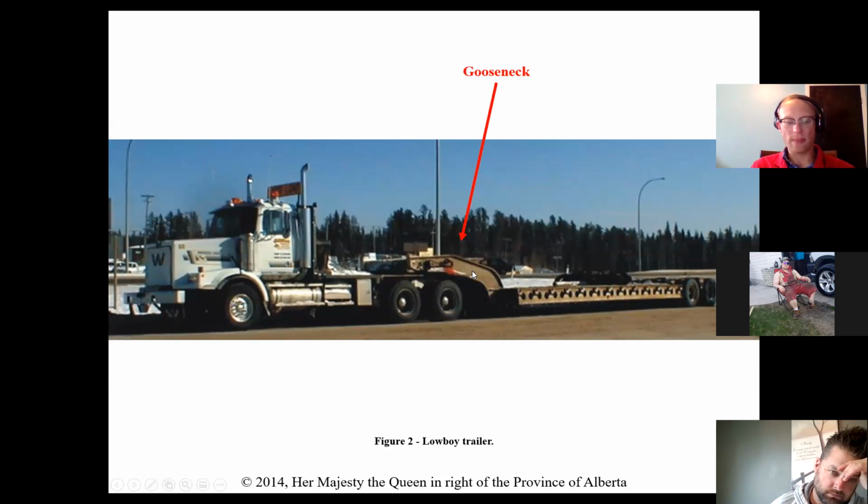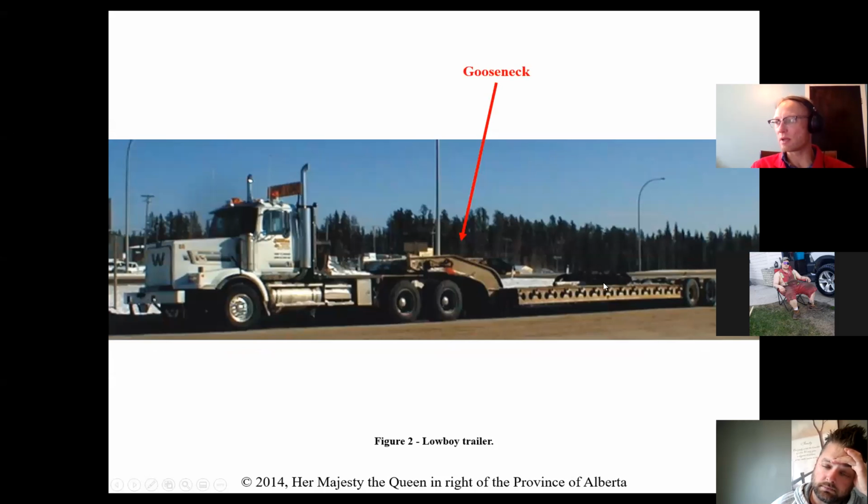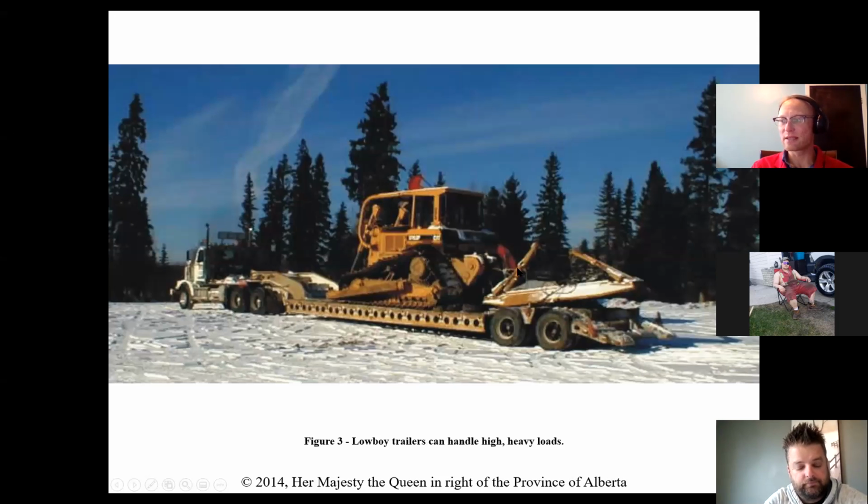This can haul like wood, something that isn't too heavy. If it gets a really high load up here, not a big deal. Whereas something that's really heavy, with a high center of gravity, you're trying to avoid that, so it hauls the load a lot lower down. You wouldn't want to put this on a high boy. Could you? Sure, it could go on top of there, but it's going to be a lot less stable. So it's all about that center of gravity, lowering it down.